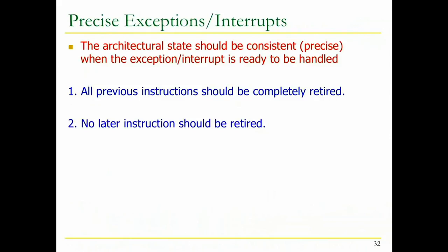And no later instruction should be retired. Basically, you have a clean slate between two instructions. Anything before this instruction is done completely and updated the architectural state, and anything after this instruction has not started yet, done nothing to the architectural state.